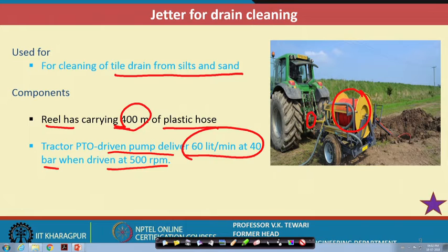It is very essential. Unless you clean, you will find that over a period this will deposit, and the flow will decrease, and hence this siltation means proper drainage will not take place. The drainage quality will decrease and the drainage efficiency will come down. The size of the drain will also reduce, because of this deposition. So, the height will decrease, and the total volume which will move through it will also come down.